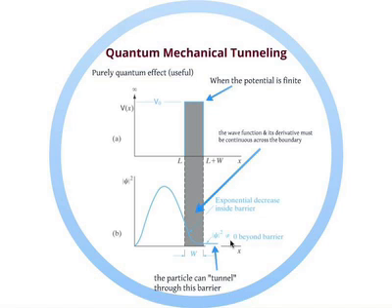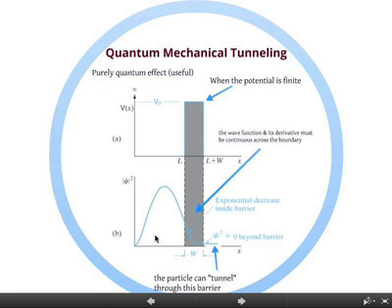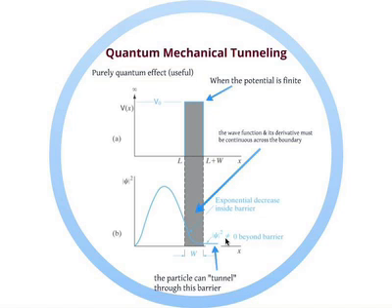And from a particle picture, the electron in here can tunnel through. There's a small probability that the electron can tunnel through this barrier. The larger the barrier, the lower the probability of tunneling through. Smaller the barrier, higher the probability that it can tunnel through. We'll come back to this when we talk about some devices called resonant tunneling diodes later on. Okay, we're going to stop here.